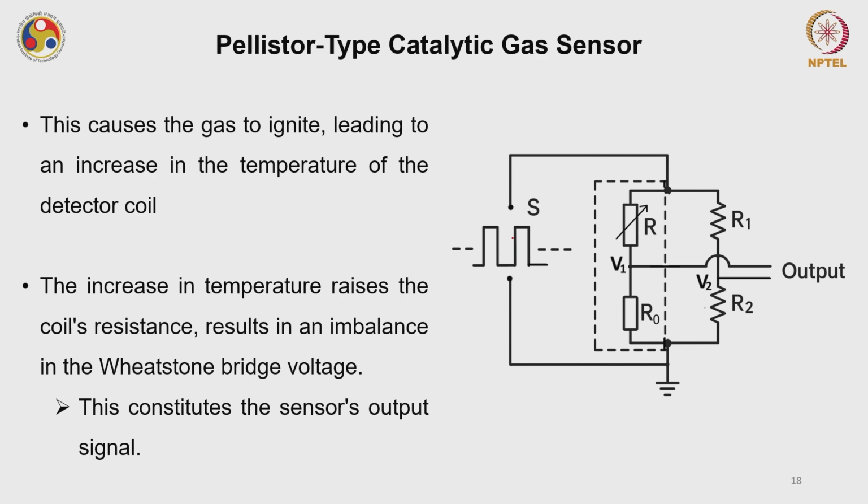For semiconductors, it should be just the opposite. Mostly you will find that semiconductors have a negative temperature coefficient, meaning when you increase the temperature, the resistance of the semiconductor decreases. Of course, this is not always true and there are exceptions; particularly for a single semiconductor, there can be some reason, because of scattering and other factors, that it also acts as a positive temperature coefficient material. But for this part of the course, let's understand that metals are positive temperature coefficient materials and semiconductors are negative temperature coefficient materials.